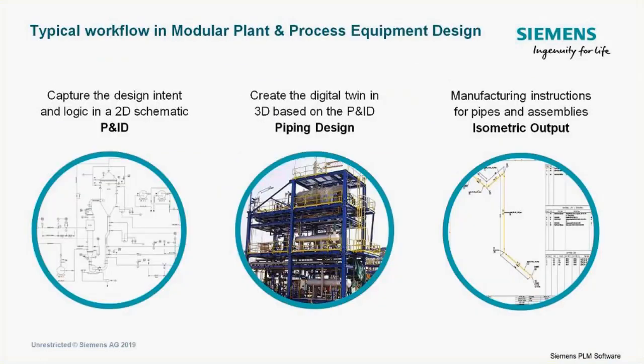So if we look at this whole process workflow, we're going to start off by communicating our designs in our P&ID, and then we're going to plan our designs with our P&ID. Then we're going to communicate how those designs work together and how they fit together to make sure that they will be able to fit in the envelope of space that you're allowed to be using, whether it be for shipping purposes, if it's going to be in a truck, on a skid, or in a container shipped overseas, various different aspects. And then finally, we need to be able to manufacture it and create it.